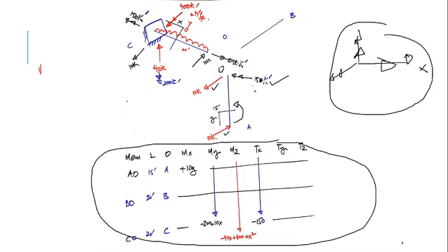So this is clockwise. Balancing 150 kip foot with an equal and opposite 150 kip foot, and similarly this 150 kip foot torsion would be taken by the support as it is, because this member is along the x-axis and this moment is along the x-axis as well. So this is torsion for this member.